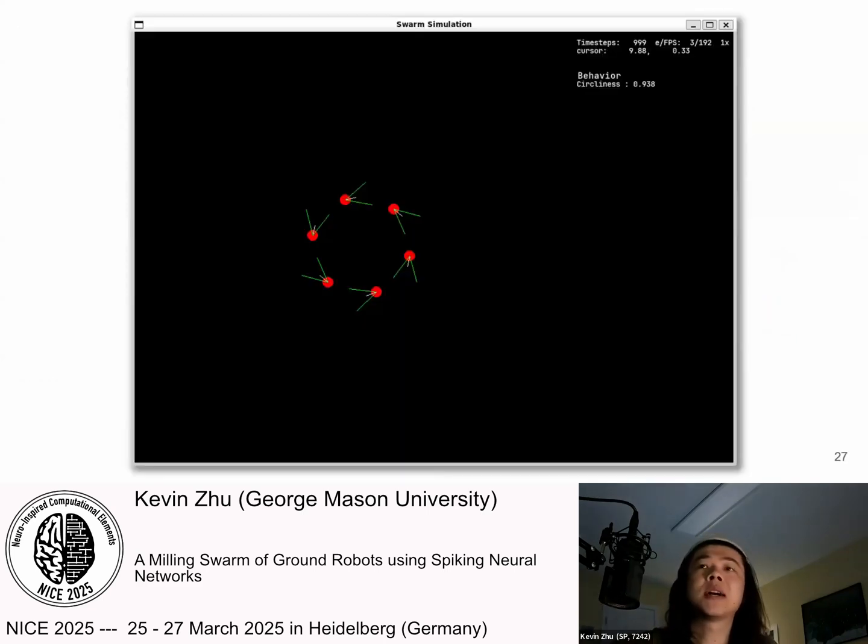So those two slides were for an older robot that we have. I haven't been able to generate those fancy side-by-sides for the new robotic platform, but that's why we have 6 robots here. We found that neither the SNN or the binary controllers had much luck for this new platform beyond 6 robots. 7 robots, even with our most finely tuned binary controller, tended to grow the circle beyond the sensing range and then collapse. So I should also note that the evolutionary process is quite stochastic.